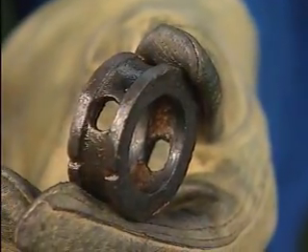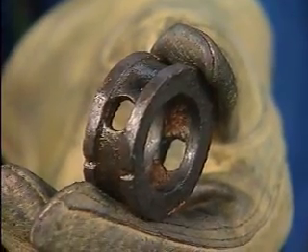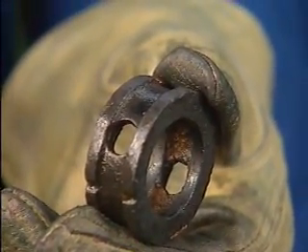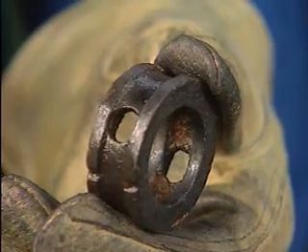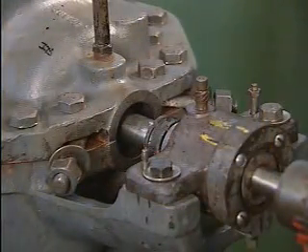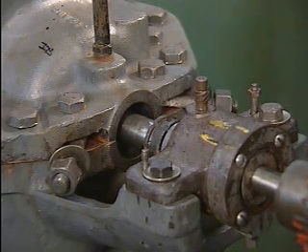box along the shaft. Many lantern rings, such as this one, are one-piece devices. In our example, the lantern ring can easily be removed from the shaft. However, in many applications, it's not possible to remove the lantern ring completely. In such cases, the lantern ring is usually tied out of the way.